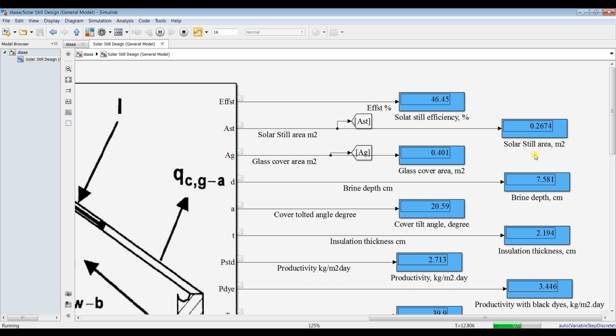I'm just opening your mind to different ideas about how to use the data inspector with a signal builder for your operating conditions. You can add your operating conditions at different moments, at different time domains, and discover the effect of that. Let's go to the data inspector and see our results.